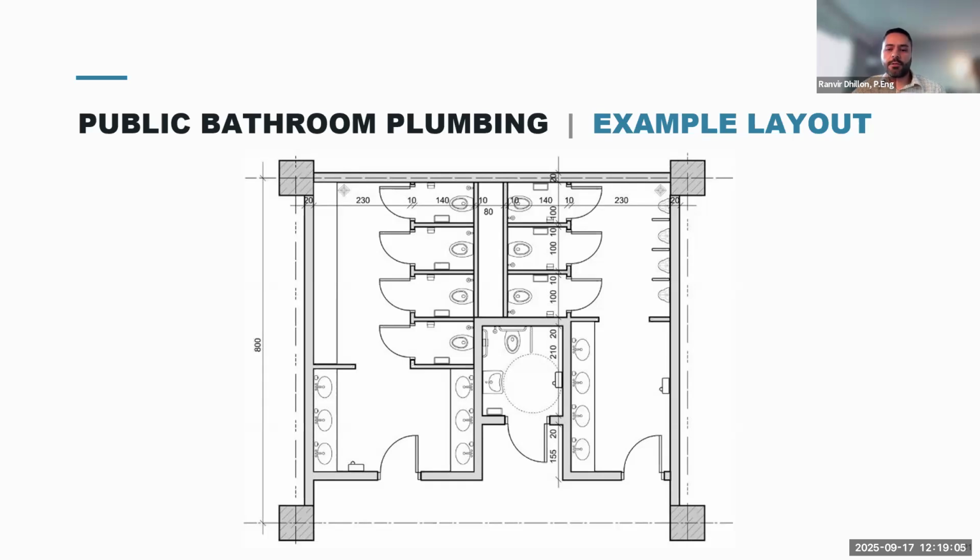Water that drains from the sinks goes through the trap beneath the fixture, then down a waste line until it reaches a larger diameter pipe, which is known as a soil stack. The waste pipe from the toilet also connects to the soil stack and to the bathroom plumbing system's vent lines as well.